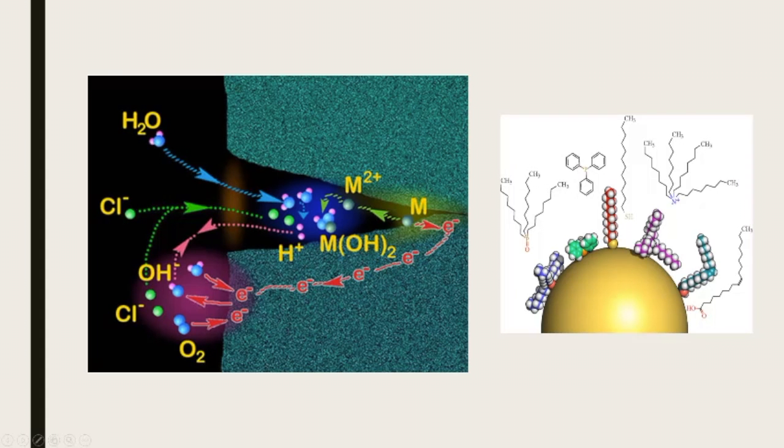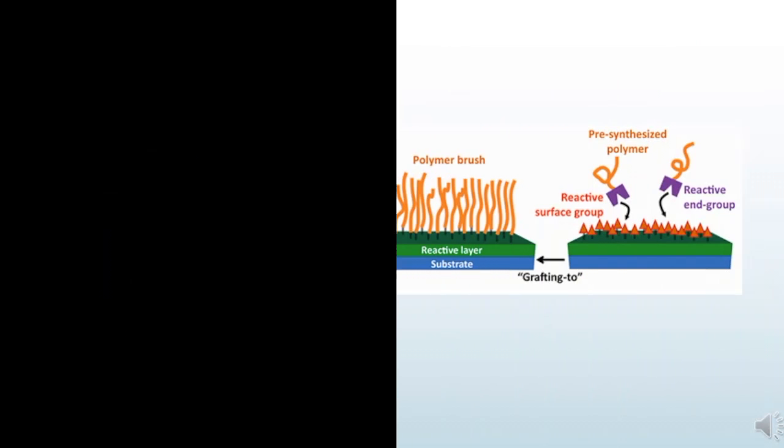So how do we accomplish all those properties for a bioimplant? The answer to this lies in surface modification. The purpose of surface modification is to retain the key bulk properties of the material while modifying the surface to improve biocompatibility. Typically, modifications can either alter the atoms, compounds, or molecules on the existing surface chemically or physically, or coat the existing surface with a different material. The following are some of the important surface modifications.